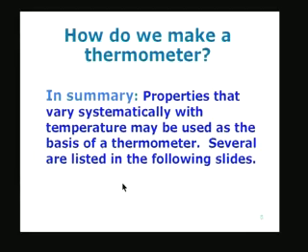So, basically ITS 90 is giving us a method by which thermometry can be practiced. It tells us about the fixed points which have been given, assigned some specific numbers which came out of a large amount of experience gathered over a long period of time, and it also tells us that different thermometers have to be used, and therefore the legitimate question is, how do we make a thermometer? What kind of a process is involved in that?